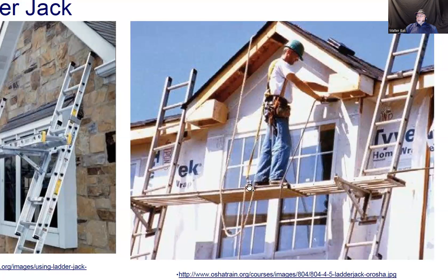Well, he's got a bit of traveling to do, which would be the length of the lanyard. And when it comes to the gravity of our planet, by the time the lanyard starts working, this person might experience quite a bit of a mechanical shock to his body. What you're supposed to be doing is tying off a little bit higher, and there's a certain height you should be tying off, just to make common sense, one thing, and the other one is to be legal, right? So you're not creating yourself a situation where I'm not sure which would be worse: falling down onto the ground or being stopped by the lanyard.